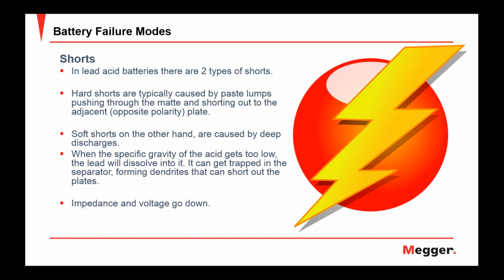That increases the internal discharge of the battery. Its self-discharge rate increases because its resistance is going down. So this is why they will fail faster and faster. In fact, as they get shorts, they get hotter and hotter, because you have more self-discharge current going through them.